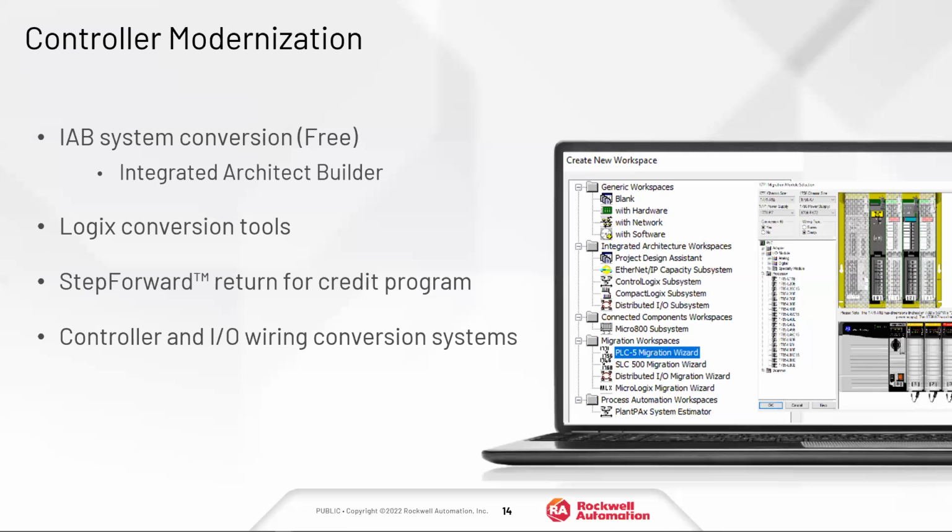Essentially what that does is it allows you to keep your field wiring in place, and you have an IO conversion chassis that will connect directly from the new ControlLogix IO, in the PLC5 migration case, to the field wiring of the PLC5.